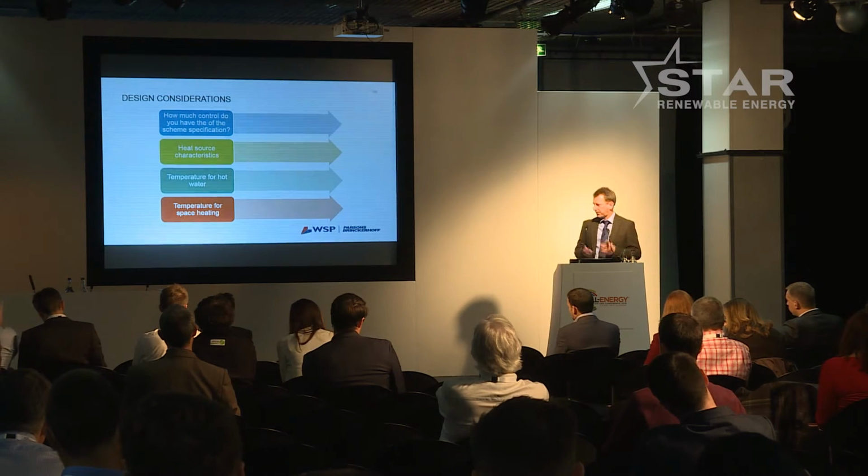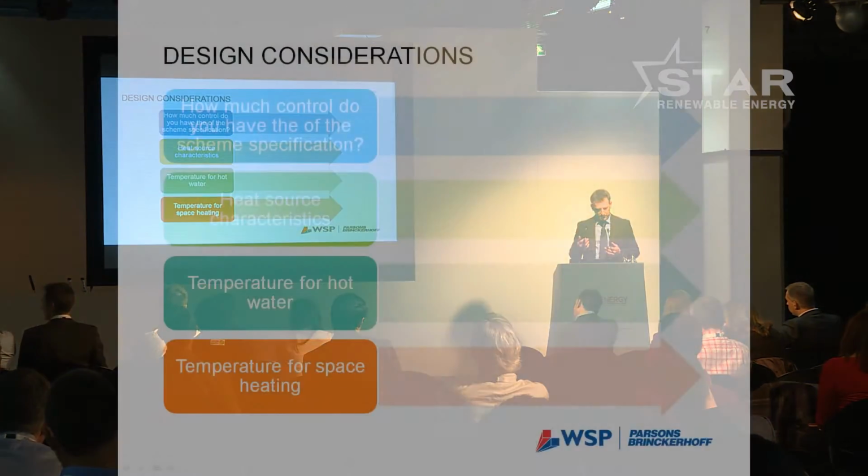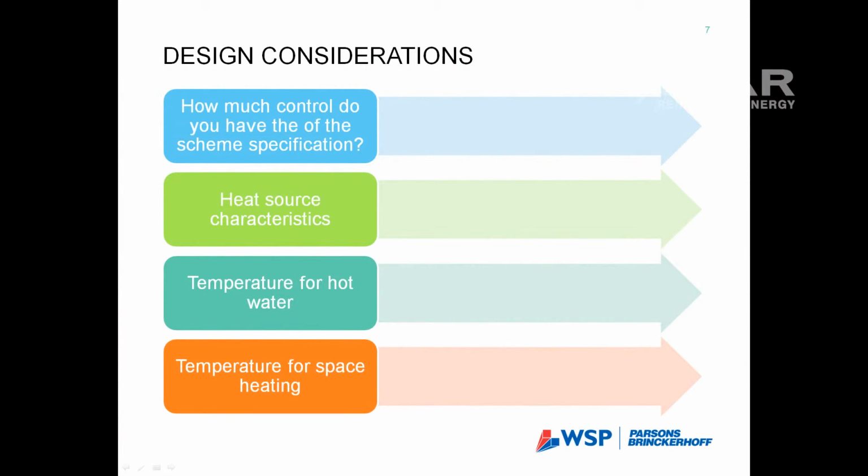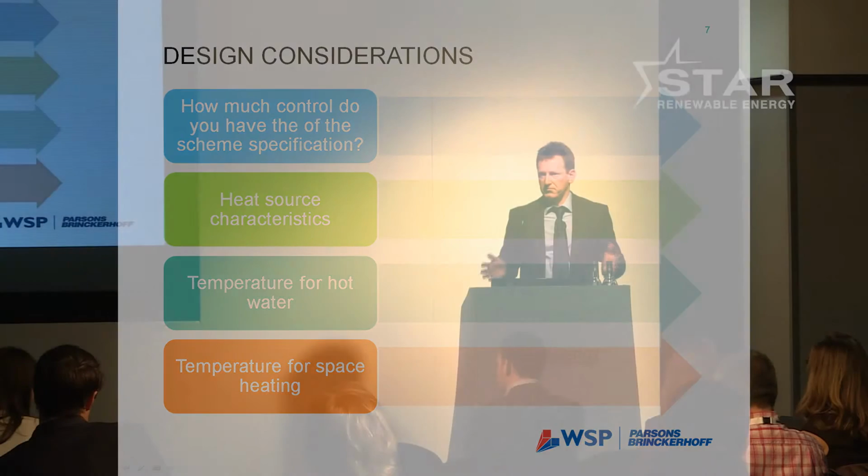And temperature for the space heating was particularly critical. It's very much driven by the heat emitters. Because of retrofitting, it had to be standard wall-hung radiators. We couldn't do underfloor heating. Physical constraints, the actual sizes of the rooms, limited how big the radiators could be.